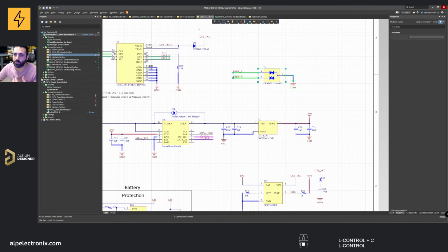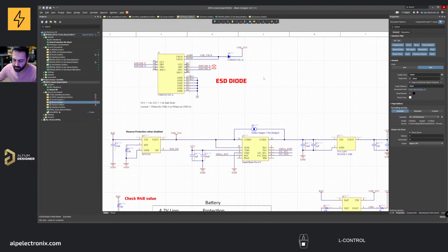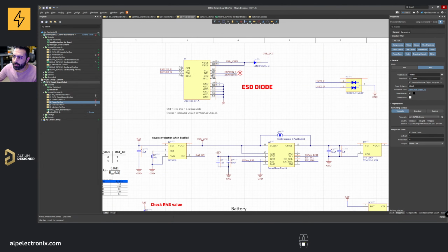We are human beings, all loaded with this static electricity, and then you need to discharge it before you touch the device. Well, these devices are hot pluggable. Hot pluggable means that you can spontaneously connect any device to the connector, and then it should recognize and just work. For example, SPI, I2C, UART, they are not hot pluggable because they will not understand when you insert that one, unless you implement a special circuit.